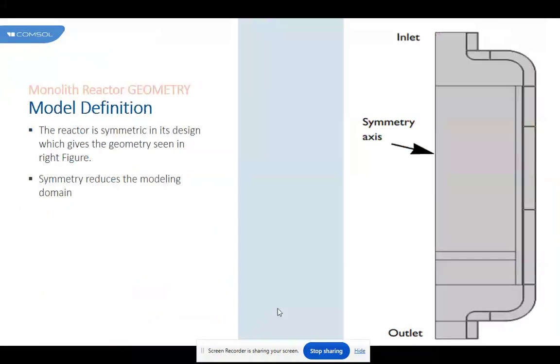The fluid transports mass and energy only in the channel direction. The energy equation describes the temperature of the reacting gas in the channels as well as the conductive heat transfer in the solid parts of the monolith structure. Because the temperature affects not only the reaction kinetics but also the density and the viscosity of the reacting gas, the energy equation is what connects the channels in a reactor structure, turning this into a space-dependent model.